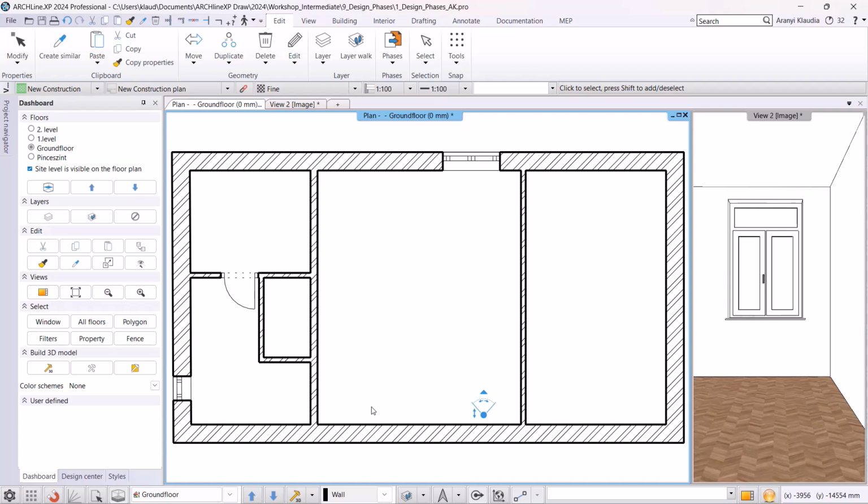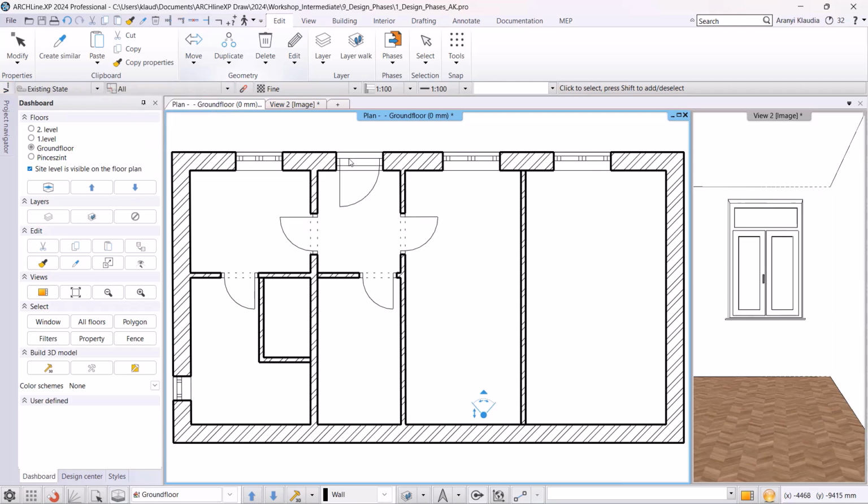In the next step, the new door and windows must be created. I will place the front doors and windows first. At the moment, it is not visible where the door and window that I designated for the demolition was. To make it visible, you have to switch to the All Face filter. The existing items are now visible.